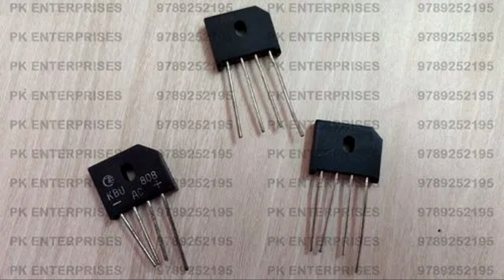Variable frequency drives, VFDs. In HVAC systems with variable speed motors, such as those used in fans and pumps, variable frequency drives, VFDs, are often employed to control motor speed and improve energy efficiency. While not directly related to bridge rectifiers, VFDs typically incorporate rectification circuits to convert AC power into DC power before using pulse width modulation, PWM, techniques to control the output frequency and voltage supplied to the motor.